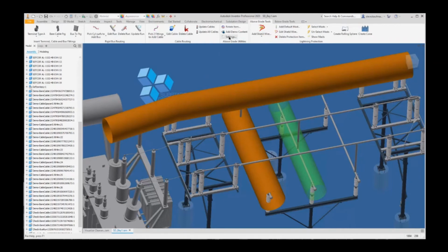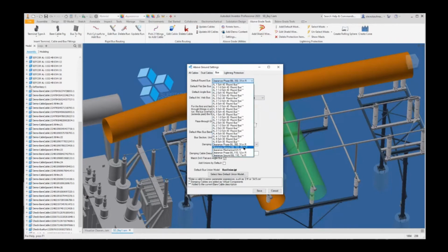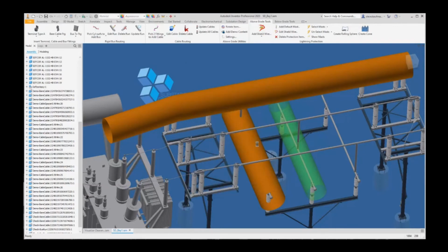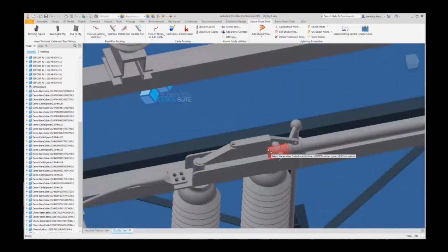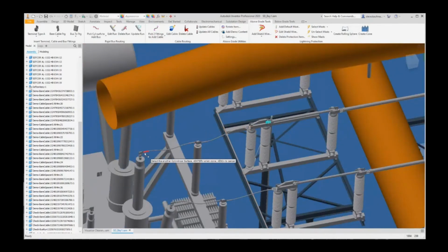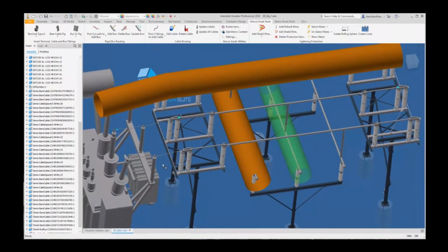I'm going to change that to the other setting for the phase to ground. We'll do it again. So we'll look at the phase to ground, which is this one, and it's only a 25-inch radius, so I'm going to change it to 25-inch radius. Well, a 25-inch offset, I should say, based on the radius. It doesn't have to be that. Whatever works for you is what you're going to use. So I'm going to have that spacing. I'll pick my cylindrical surface, and I'm going to end down here at that fitting. So we'll place the ground one as well.